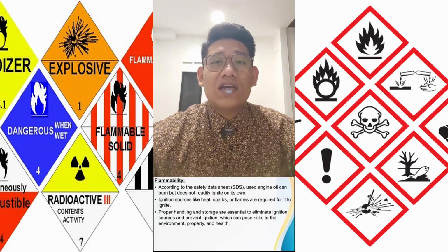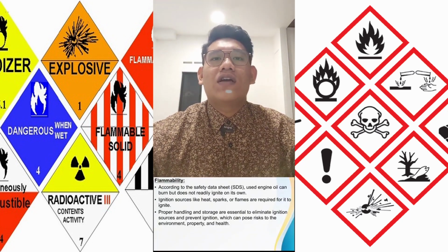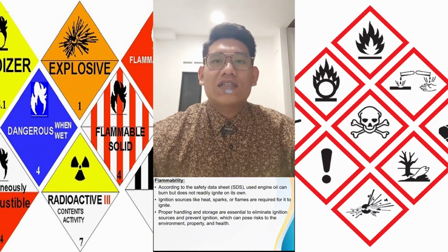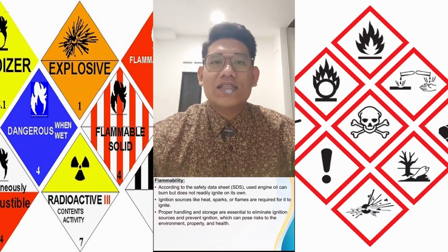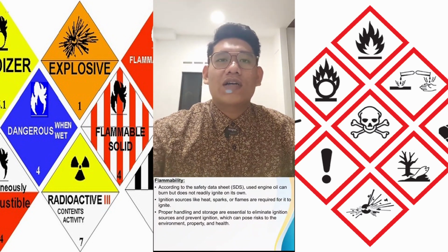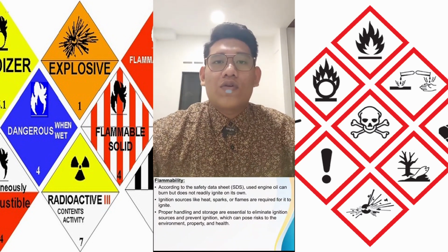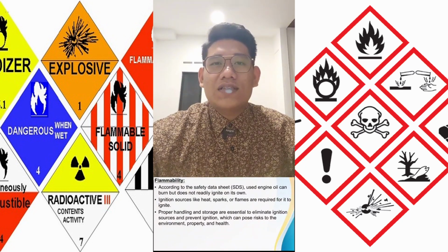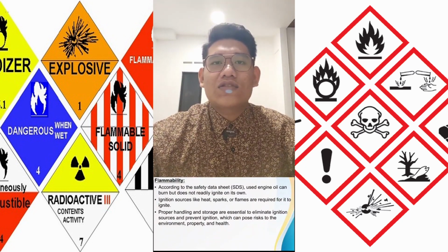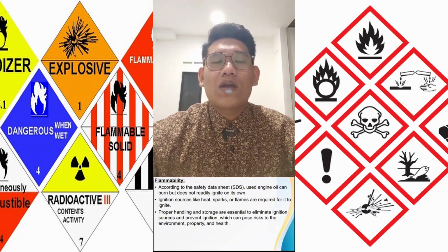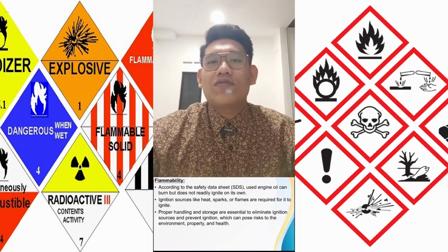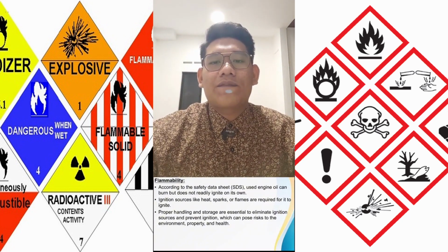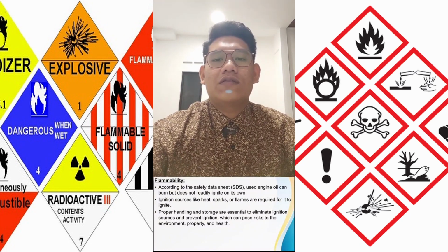Next is flammability. According to the safety data sheet, used engine oil can burn but does not readily ignite on its own. So it cannot ignite by itself unless there is a source of ignition like heat, spark, or flame. Proper handling and storage are essential to eliminate these ignition sources and prevent ignition, because when ignition happens, it can cause risk to the environment, property, and health. Thank you. That's all from me.